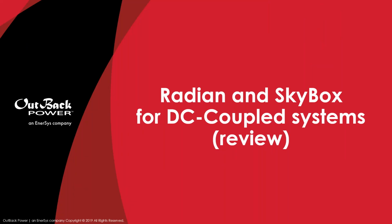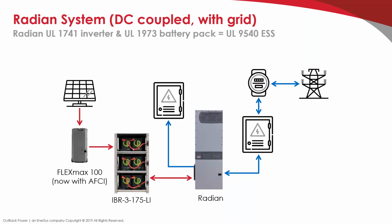Okay, so we're going to talk a little bit about Radian and Skybox DC coupled systems, just a little bit of review here. So when we talk about DC coupling, we're talking about how we couple in the PV, right? So the PV goes through what we call a charge controller, or a solar charger, if you will. It's a DC to DC converter that regulates the variable DC up on the array into a highly regulated DC for the battery charging.